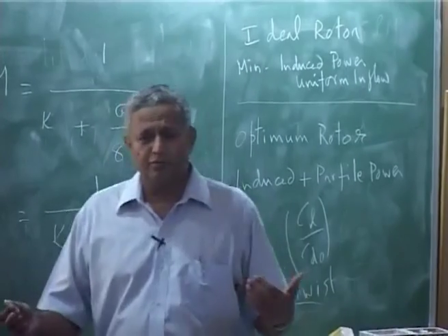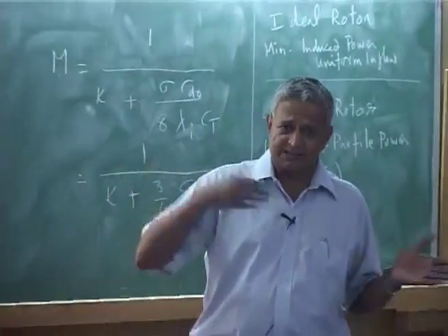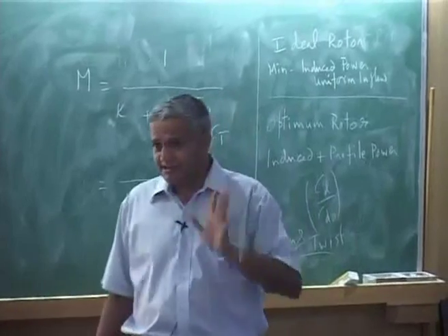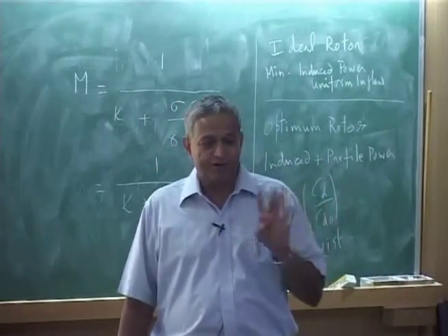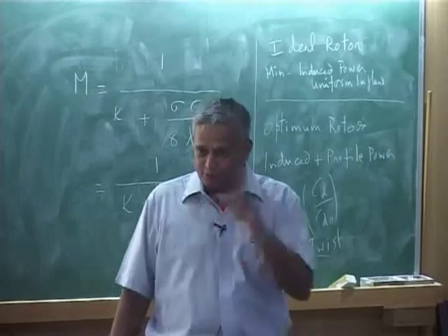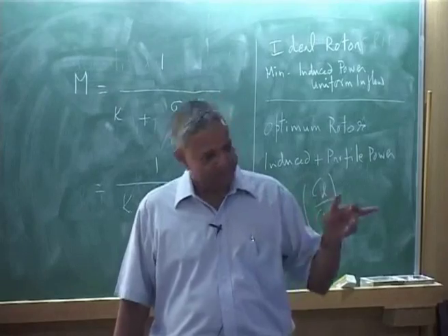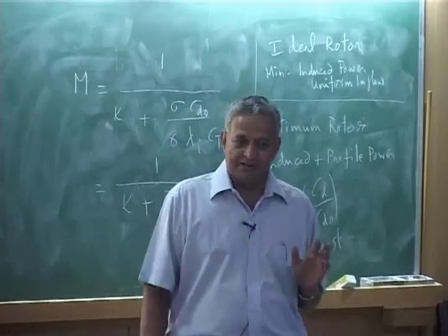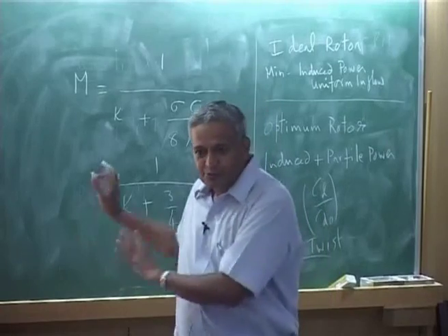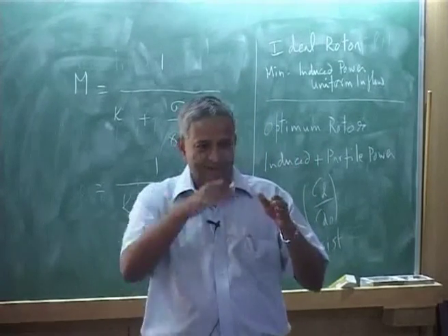Of course, if you want to calculate the losses, the tip loss, etc. Now I have given you an assignment in which I gave you four cases of blade: one no twist, another minus 10 degree linear twist, another minus 20 degree, then ideal twist. For this, if you use whatever we have derived, I have asked for 5 plots.